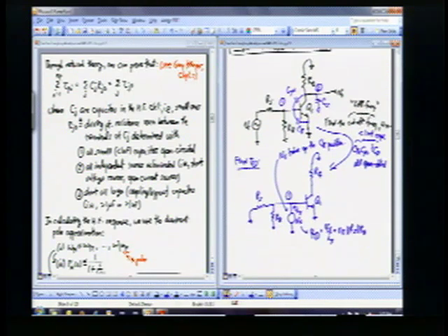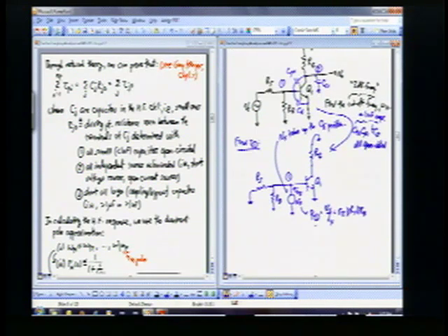And so if that's my driving point resistance, now I can write down an expression for that first time constant, tau 1. That's just going to be equal to the capacitance that I replaced with this voltage source Vx, which was C-pi. That was all the capacitance going to ground. You notice C-pi is not just going from the base to the emitter here. It's going from the base really to ground, because the emitter is grounded.